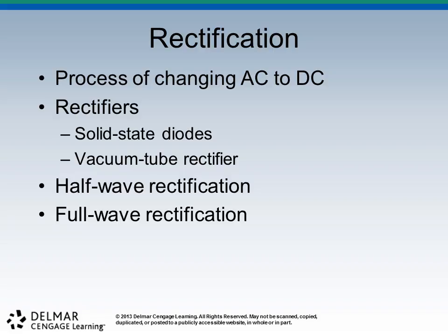What we're trying to do with our rectification, just go ahead and turn to page 96, and you're going to see B, figure 5-7B. What we're really trying to do is rectify that and then get three separate incoming AC waveforms so that we've got a very small amount of voltage ripple. You see that there on the right? So what we have is a full wave rectified three-phase unit. So the power never drops to zero. And again, I know I'm getting ahead, but it's hard to talk about one and not talk about the other.